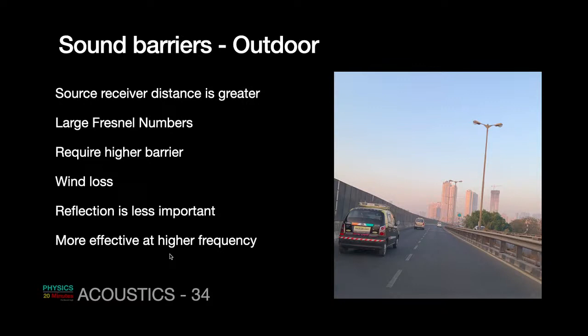So the smaller the wavelength, the larger is the Fresnel number, and therefore more is the attenuation. So higher frequency gives a smaller wavelength. These barriers are more important at smaller wavelengths or higher frequencies.